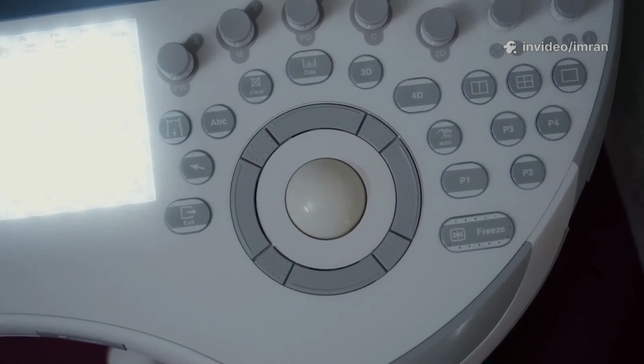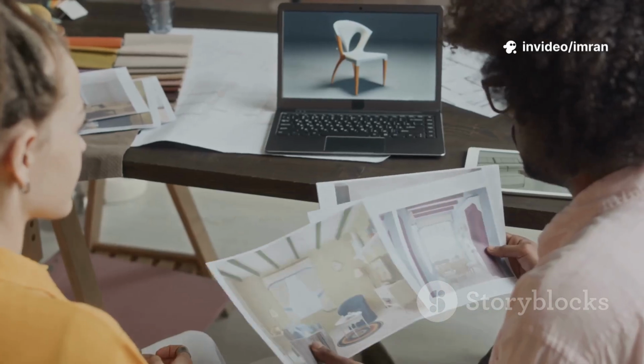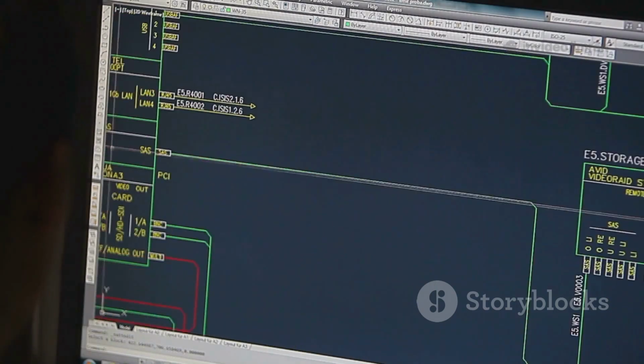The Move command relocates objects. Select objects, then specify a base point and a second point. Use object snaps for accuracy. The Copy command duplicates objects. It works like Move but leaves the original in place. Create multiple copies until you press Enter or ESC, efficient for repetitive elements.